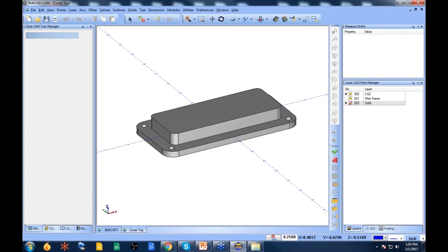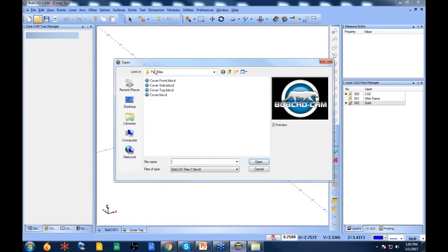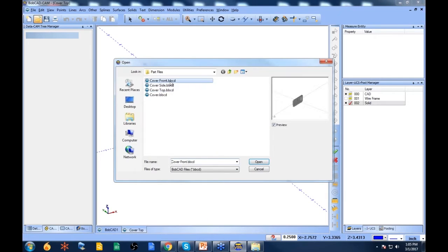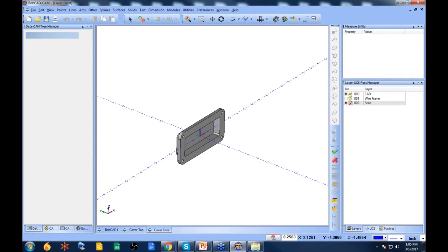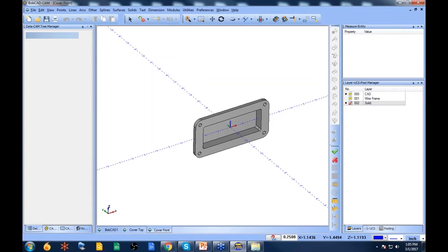If you're bringing in SolidWorks files, a lot of times they come in the wrong orientation. If we look at this, a lot of times if you're coming in from SolidWorks, our top view is their front view. Okay, so when this happens, you know, what are the steps that you take? What can you do? How can you deal with it?